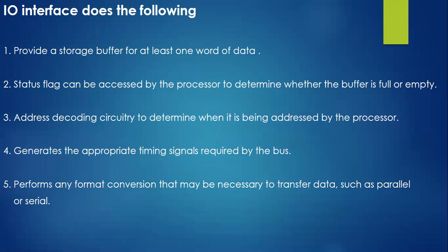So in today's class itself, we will be discussing that. But for the time being, the interface circuit will allow the processor to access the status flags. Fine. Later, third point: an address decoding circuit to determine whether the device is being addressed by the processor.